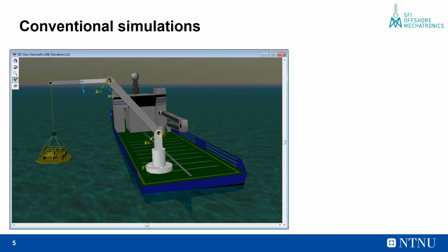Simulation of offshore load handling operations can be carried out using software like OrcaFlex, where the control variables are the length of the winch wire, the tension in the winch wire, as well as the position of the constraints which model the linkages of the crane. This means that we can carry out simulations involving the raising and the lowering of the payload while accounting for the effects of the change in the orientation of the linkages of the crane.